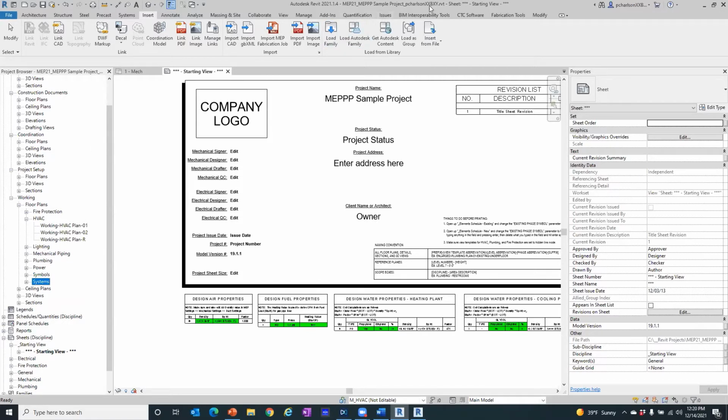Now, again, this is the sample project. The actual template has it set up so there's 8 default levels within it. So depending upon the type of projects that you work on, you can scale that back. You're always able to fully modify the template that you get. And if you're only working on 2-story buildings, well, you can cut some of those levels out of the project so that when you start a new project, you don't have to go in and delete all of that information.